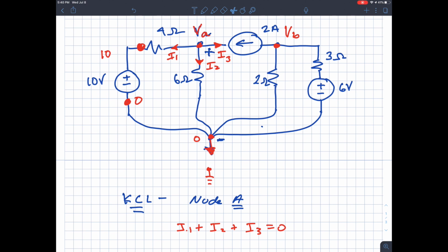Now I'm going to also choose this dot. This dot is VA, and this dot is 10. I slid it along a wire. If it started out at 10, it stays at 10 because it's along a wire. It's like sliding along a flat part of an elevation. So I take VA and I slide that to the other side of the resistor.